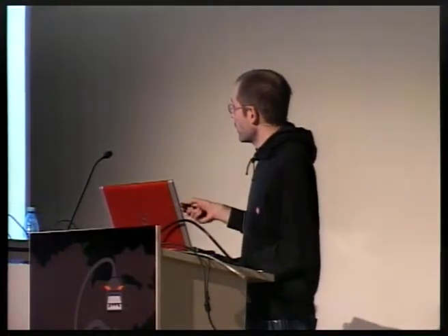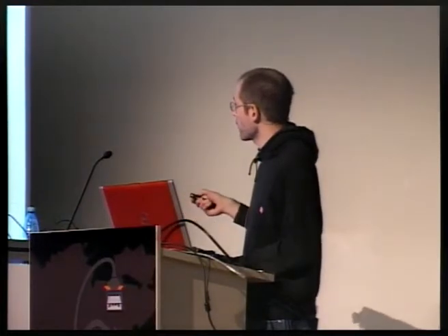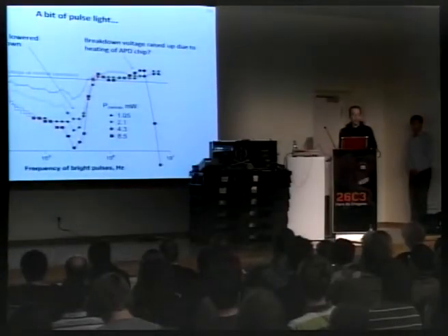You can see on the right part of the figure that there's another region where you can control the detector. And surprisingly, the bias voltage is back to the nominal value. So you could say, hey, how can you control the detector here when the bias voltage is, again, around or above breakdown voltage? It should work again as in Geiger mode. And the assumed reason for that is the following. When you apply very bright illumination, you start to heat the APD chip.